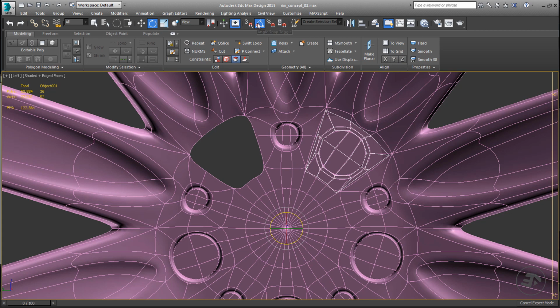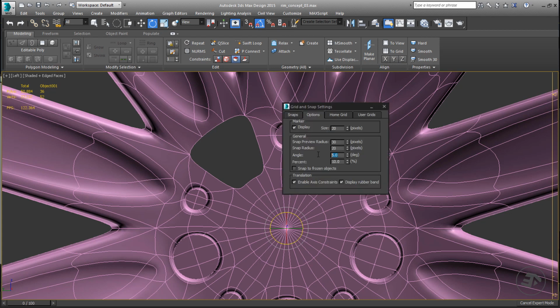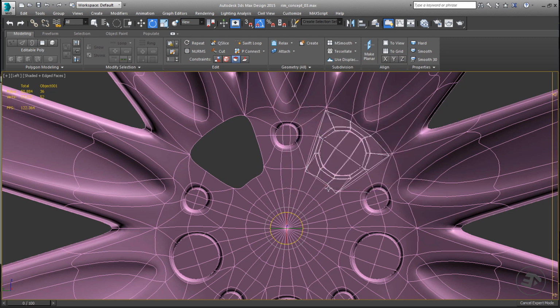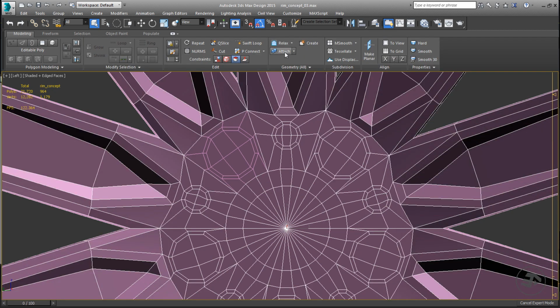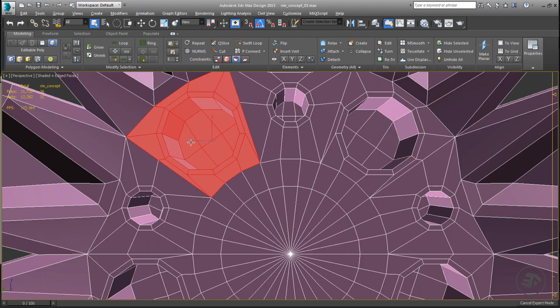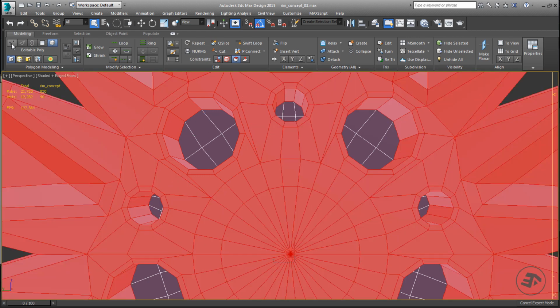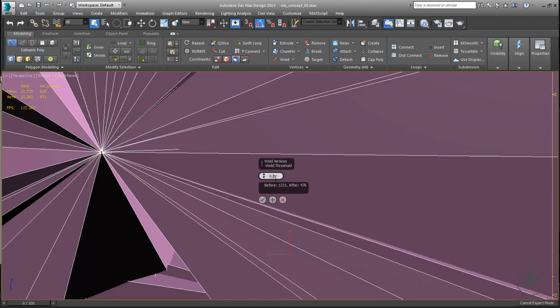With View as reference, and the tool at the center of the world. Enable Snap to Angle, and change the snap angle to 72 degrees. Attach the object to the rim. Weld the selected elements as shown.